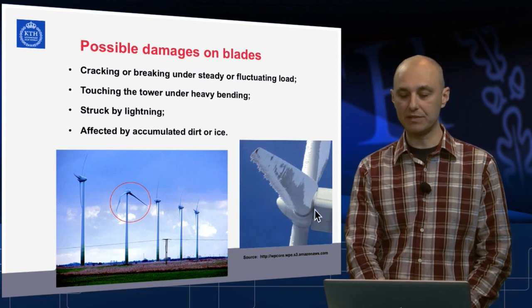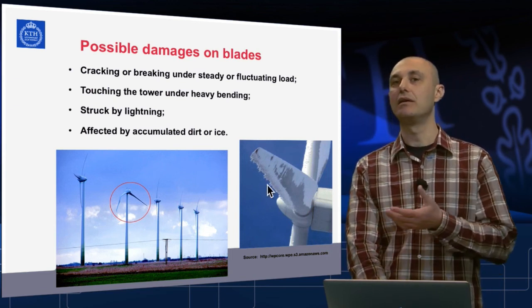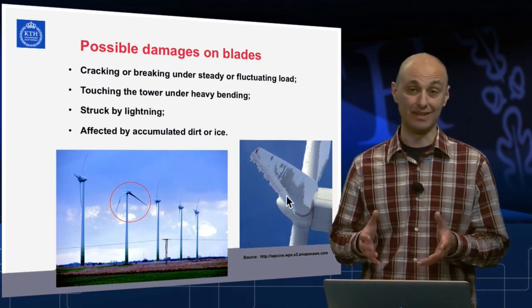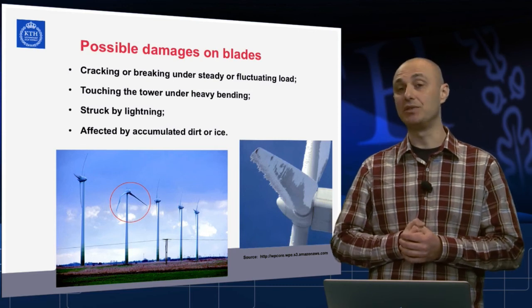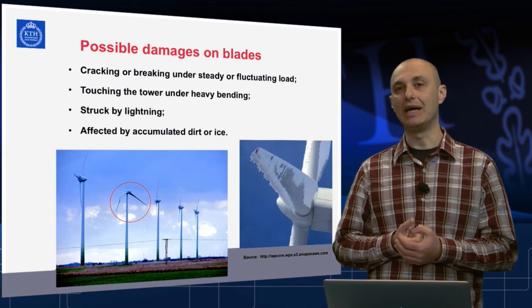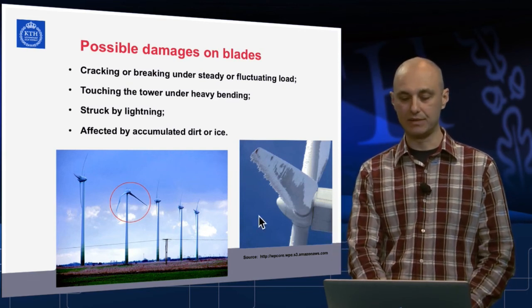So one of the blades vibrates in one mode, the other blades in another, and the whole turbine is ruined. It may not be ruined immediately, but definitely the lifetime of the machine will be decreased if you allow it to operate too long with iced blades or ice-loaded blades.